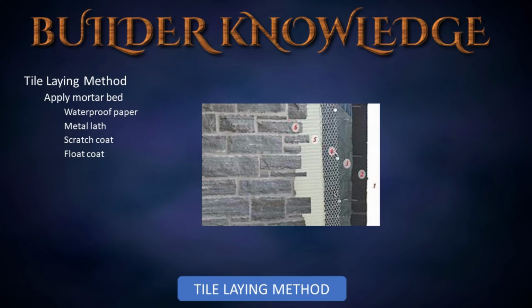First, you apply a mortar bed. In order to do this, we start by tacking a layer of waterproof paper to the studs. Then nail metal lath over the paper. And then apply the scratch coat. Make and mix scratch coat to 1:3 parts cement and sand, with an additional 10% hydrated lime by volume of the cement used. While still plastic, scratch and cross-scratch the scratch coat.